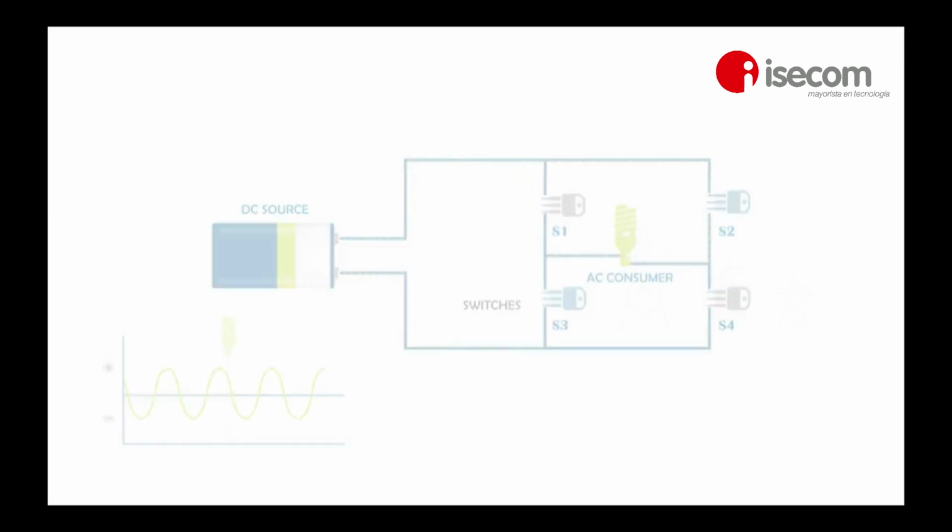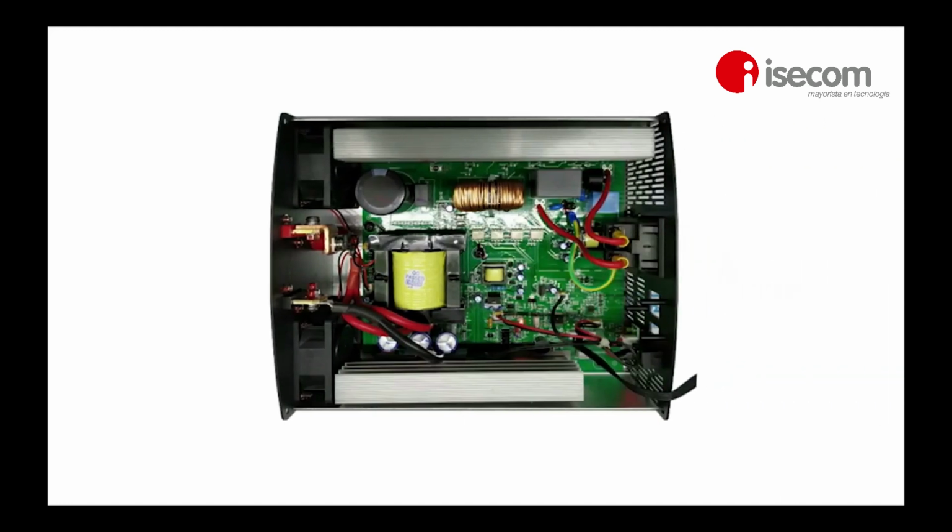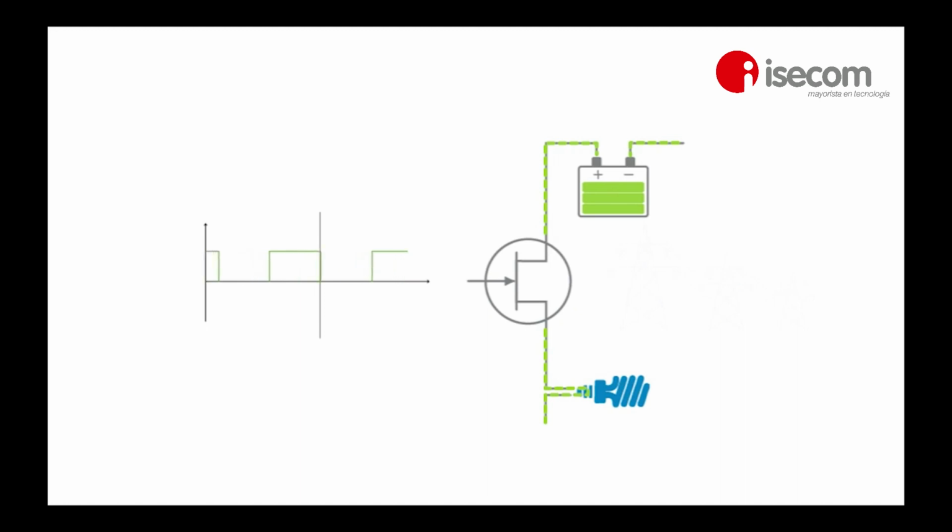To better understand how an inverter works, let's look at the interior parts of it. Basically, the PCB can be divided into 4 main parts. The whole procedure is to take a DC input here and deliver the AC output here. At part 1, switching occurs and the square wave is generated. So instead of the mechanical switches described, electrical switches such as FETs and IGBTs are used to perform switching. These elements usually have a high-frequency switching capability. They require control pulses to switch on or off, and these pulses are generated by a control circuit.